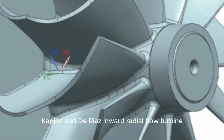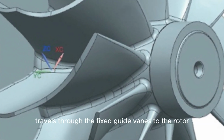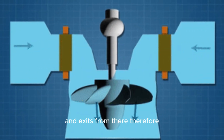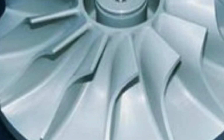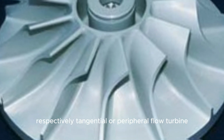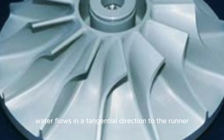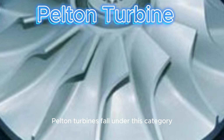Inward radial flow turbine. Water enters the turbine casing through a penstock, travels through the fixed guide vanes to the rotor, and exits from there. Therefore, the inner and outer diameters serve as the outlet and the inlet, respectively. Tangential or peripheral flow turbine. In these types of turbines, water flows in a tangential direction to the runner. Pelton turbines fall under this category.